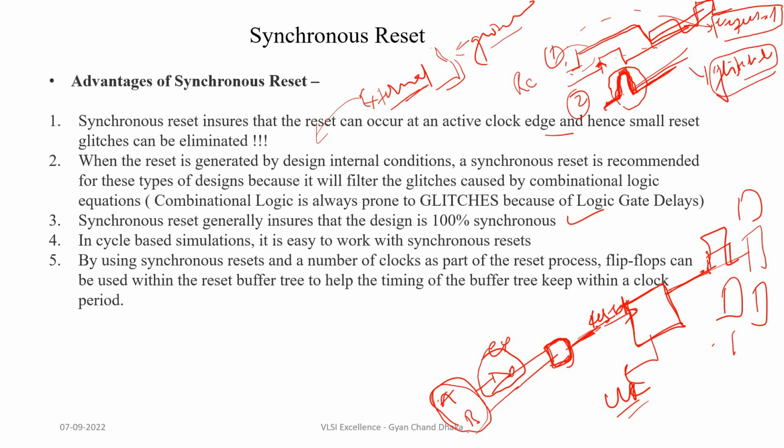The further advantage is in cycle-based simulation, when everything is evaluated based on clock cycles, and everything is updated or processed at every clock cycle. It is easy to work with synchronous reset because we can update everything based on clock cycles. So in cycle-based simulation, it is easy to work with synchronous resets.